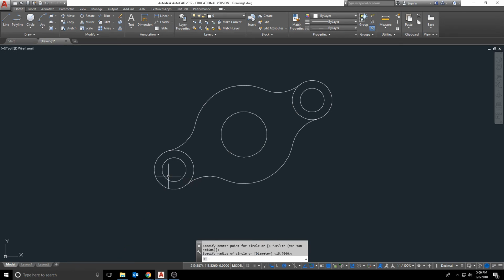So here we've got exercise 3-20 completed, and it makes it go a whole lot faster when you actually use the circles as opposed to trying to get an arc to fit between those. So in a lot of cases where you want to actually create an arc, it's going to be much easier to use the circle command. So this is exercise 3-20.